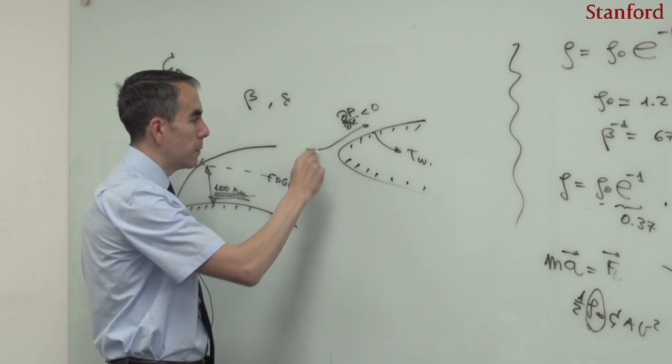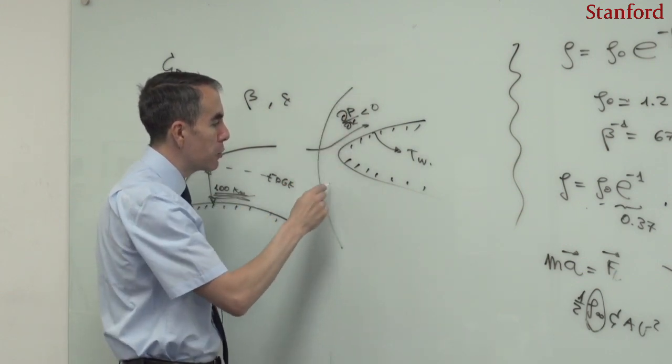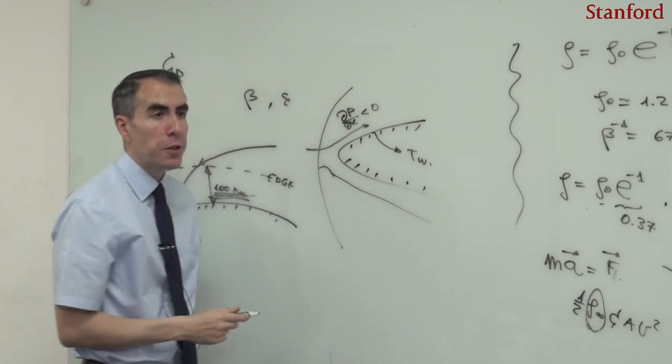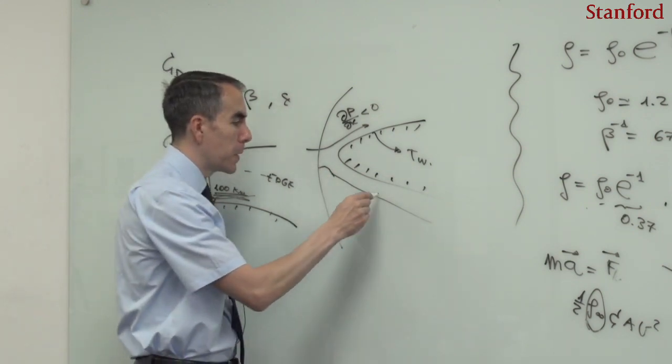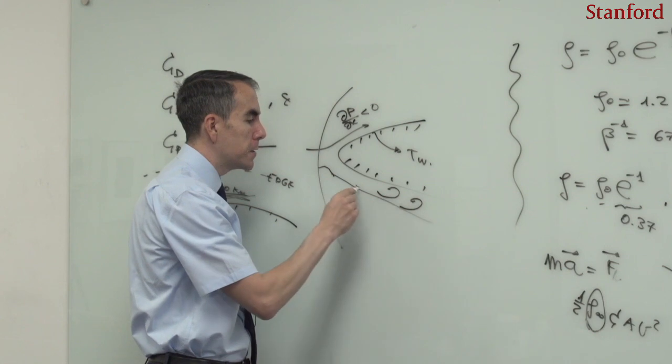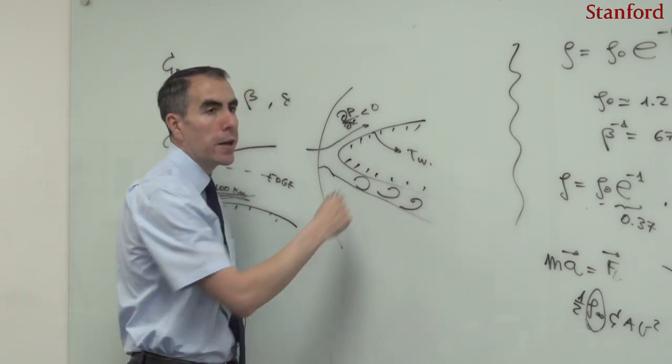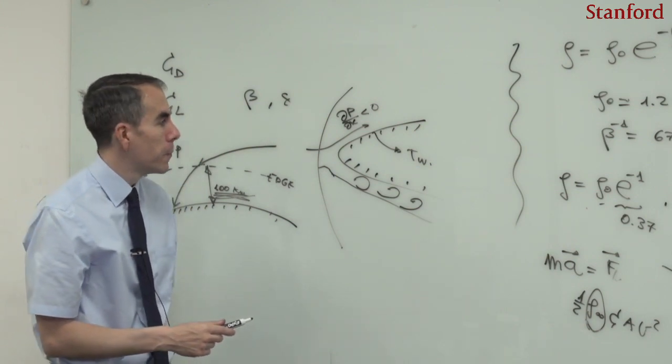Third is that because of the shock wave that is produced here, one has an entropy layer developing, as we discussed 2 lectures ago. This entropy layer has a vorticity, and it's a stabilizing vorticity. So because of this entropy layer, the boundary layer transition is also delayed.